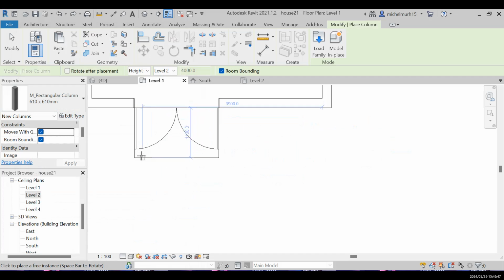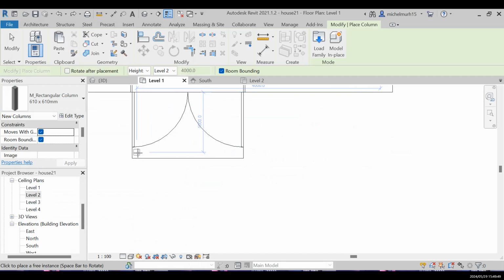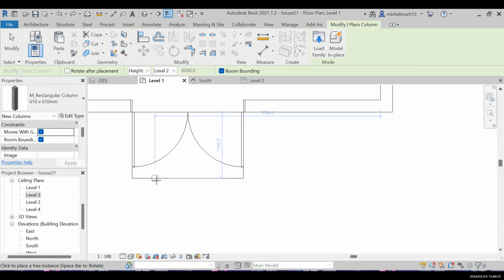Like here, I'm gonna put one of my columns here. You can see the dimension, right? You can see it's 4,000. Okay, let me do this for you guys. So you can see here, right? I will take 4,000 here. X direction should be 4,000, and Y direction should be 1,000. So I'm gonna press in here, and I'm gonna follow the same line until I reach